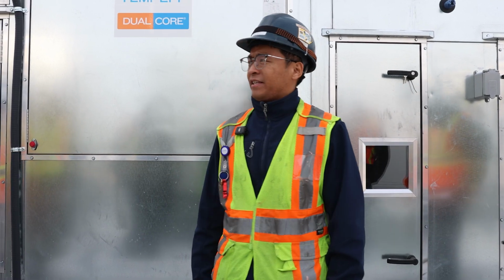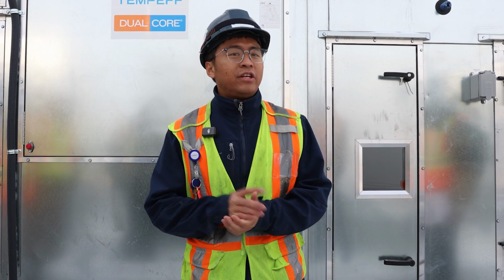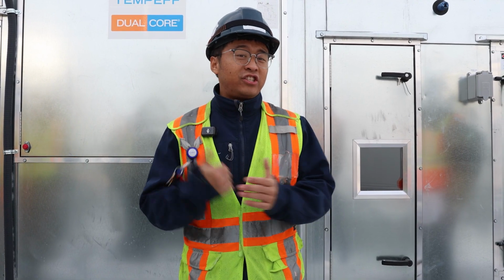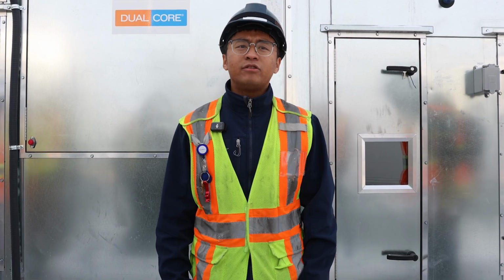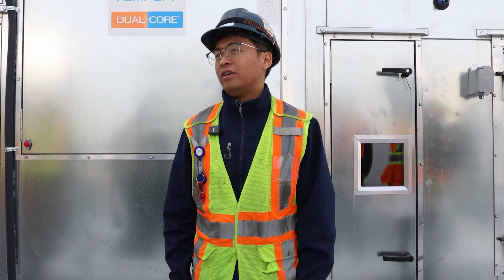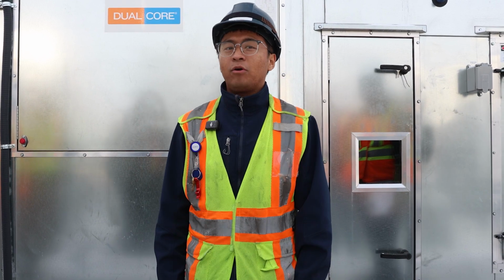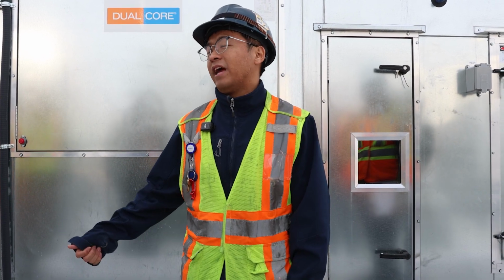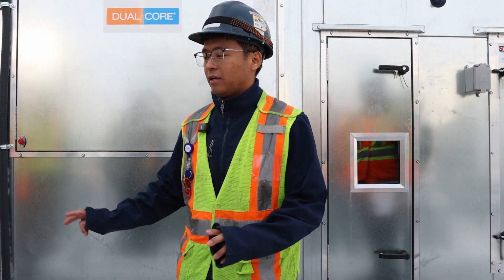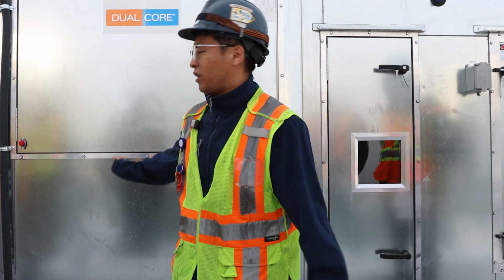We have the sensor for supply air for sure, and also the discharge and return humidity. Outside air temperature will not be from this unit. It will be the building outside air temperature. I can show you that later once we get there. Yes, we pick up the smoke alarm from the fire alarm panel. If the fire alarm sees any smoke condition, it will send it to the BMS. BMS will turn it off.